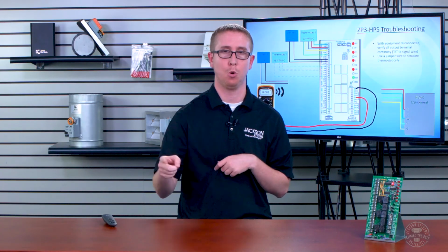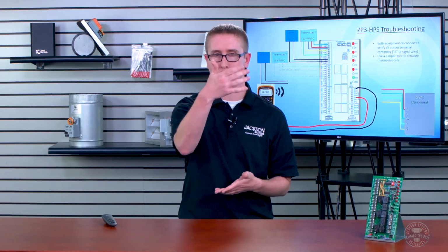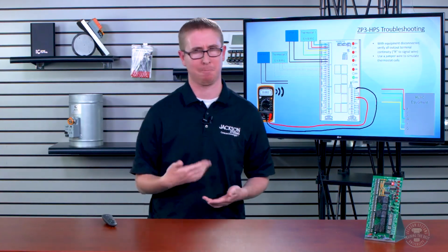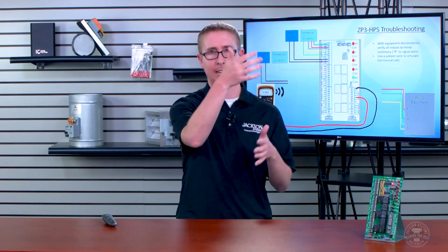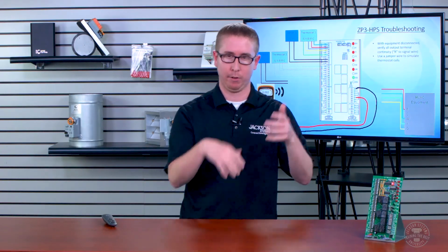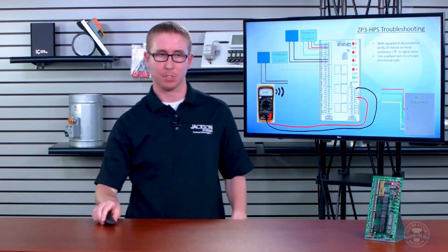The 6 zone panels, again, both the standard and the ESP version, they have an option. You can either choose cooling priority, which obviously would mean if one zone's calling for cooling and 3 are calling for heating, it would still output cooling because you chose cooling priority. Or you can choose majority wins, which is the much more popular choice. And that would just mean in that same scenario, 3 for heating, 1 for cooling, heating would win because 3 versus 1, majority wins.